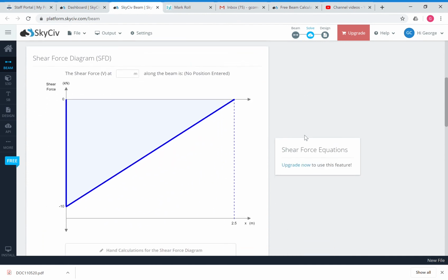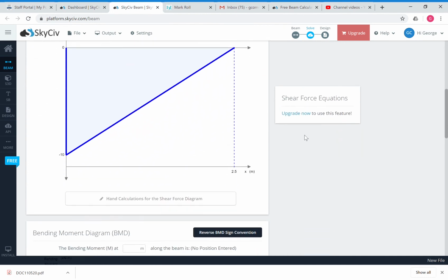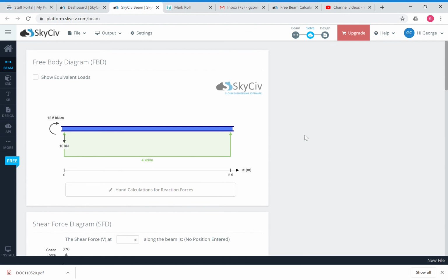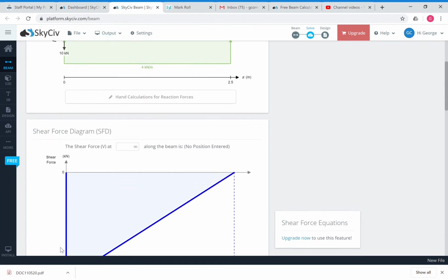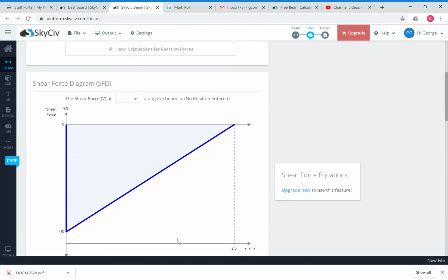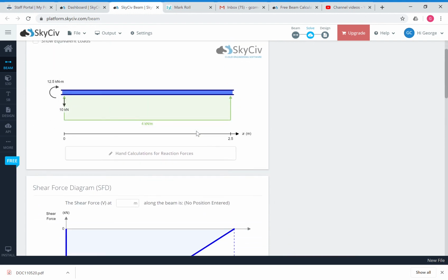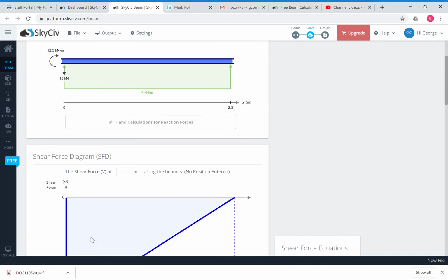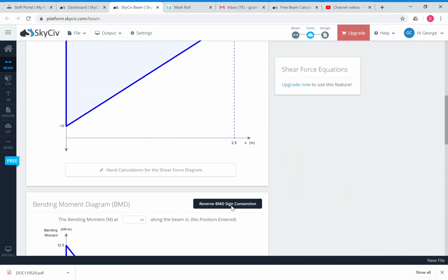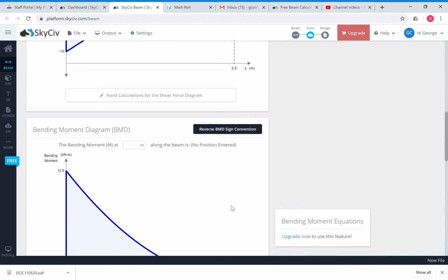So shear force is negative once again, so we've just followed the force down at the wall, the reaction down, but instead of coming straight across like we do for a point load until we get to the halfway and then come back up, what they've done is they've just followed it all the way down to 2.5. Okay, so it slowly gets less and less, because eventually when you've got no distance between the two force vectors, you have no shear force. So that's what the shear force looks like.